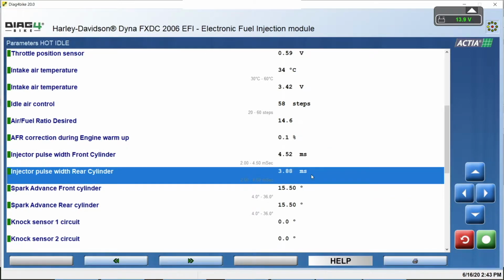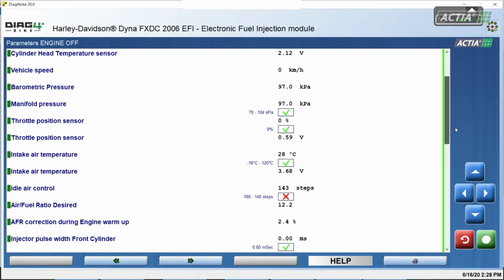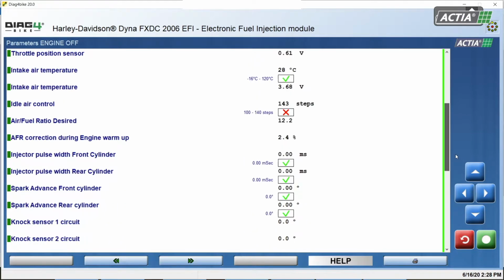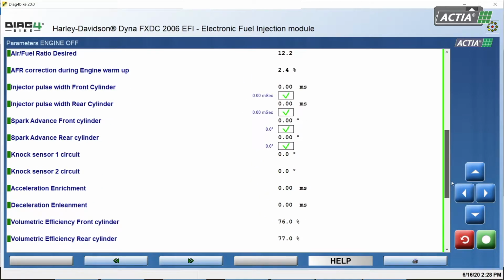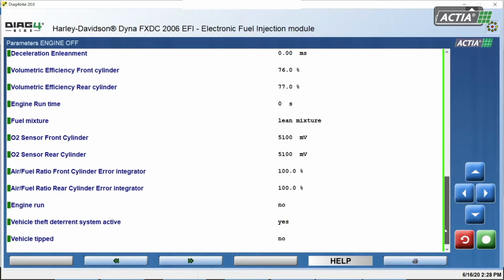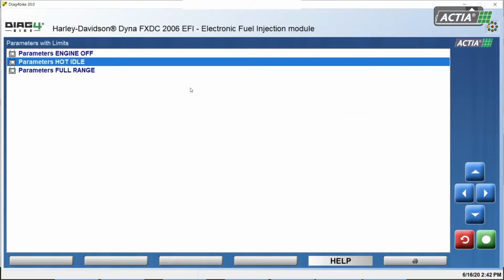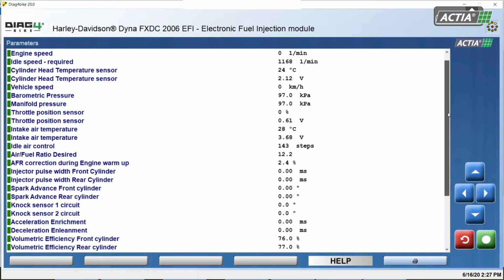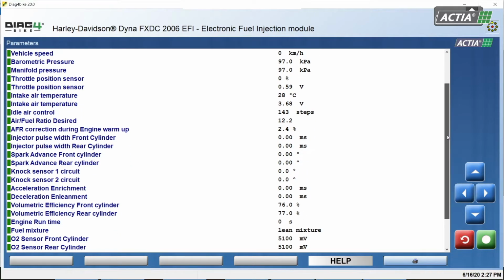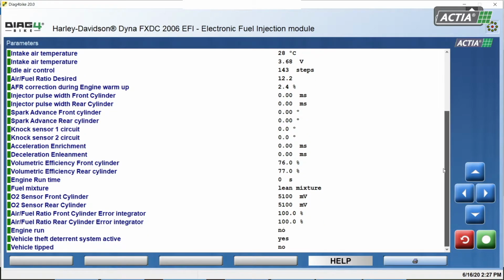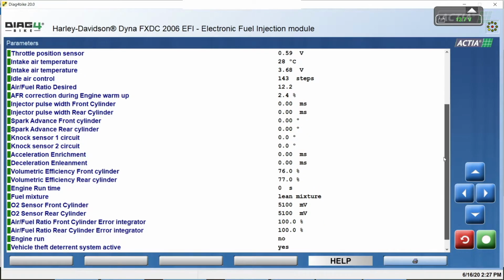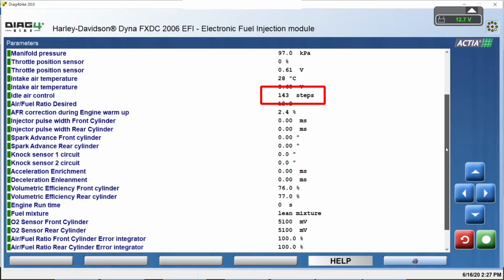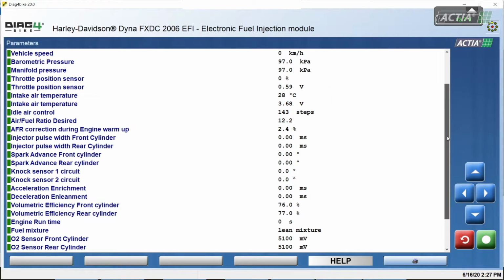Parameter reading with limits is an advanced operation that constantly updates. Here, the parameters are accompanied by information about standard or recommended limits. It allows the operator to quickly evaluate major deviations of parameters in particular. Parameter reading can often uncover hard-to-find faults, such as the causes of erratic engine idle by evaluating the state of the regulator of the idle system during controlled idle running. These causes can be easily revealed by reading the state of the IAC step motor.